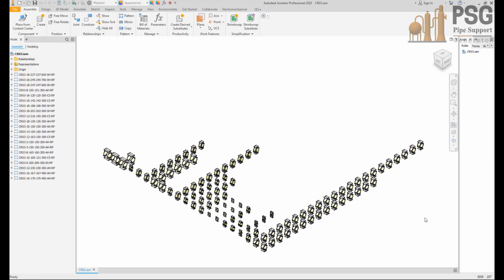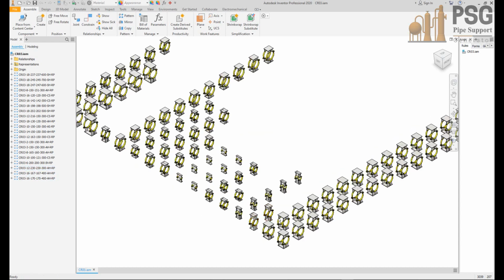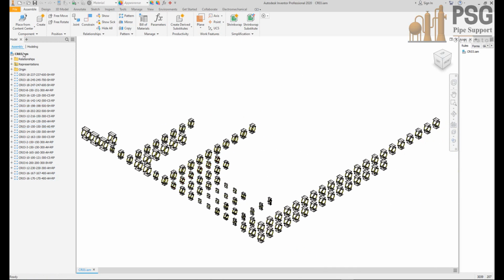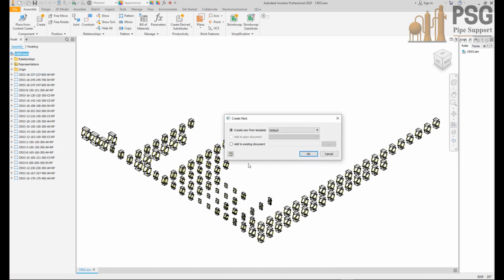Now let's go to the last part of this session, which is part number 6, calculating the raw material required for plates by using the Autodesk Nest tool, and how we will do that. Now we create the final assembly for the support group. From the assembly tab, let's select create nest, and after getting this form, let's select standard bill of material.